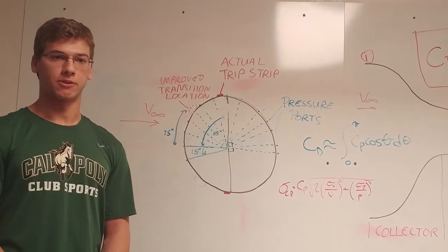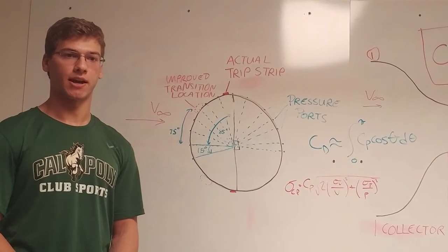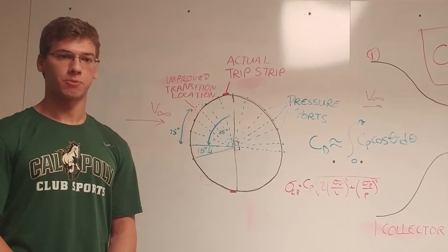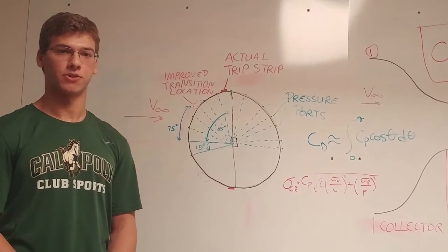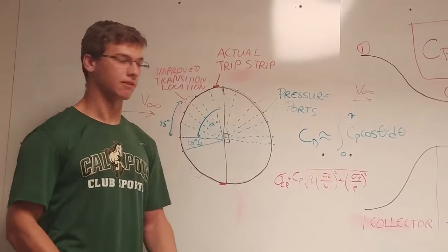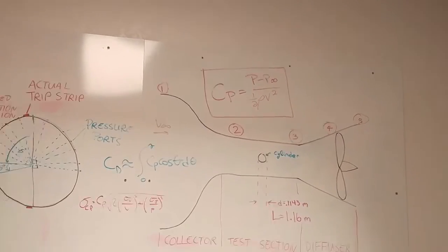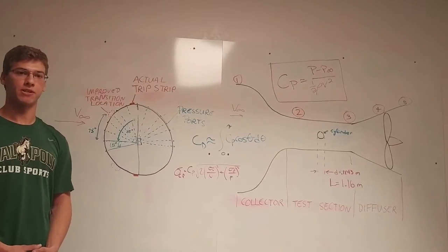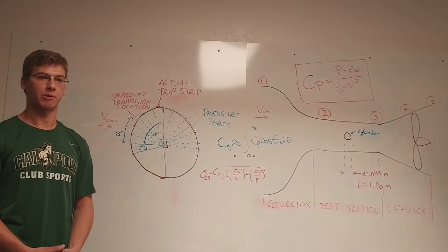Because our main concern here, data-wise, was looking for a coefficient of pressure and drag calculations, it was important to understand our pressure measurements. We used static pressure ports, which means our pressures obtained were referenced to the free stream pressure. Thus, our data is essentially P at the port minus P infinity, as shown in the equation above here for coefficient of pressure. This makes calculations for pressure coefficient very simple, as it requires only dividing by 1/2 rho V squared, or dynamic pressure.